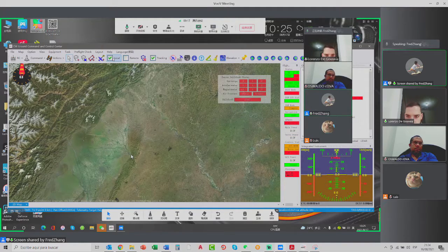But the remote flight plan means it is already sent to the autopilot. You cannot edit anything, you can only move the waypoint position. And the color is blue. All right, so this function is clear remote. When you connect with the craft and click it, it clears all the autopilot flight plan. Tracking, we must tick it.